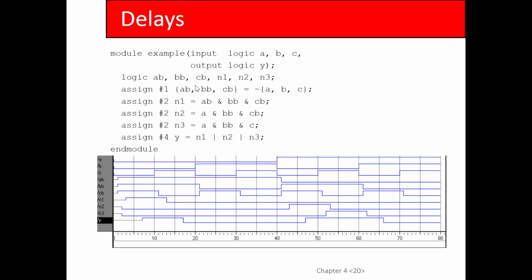The problem is that this Verilog is now non-synthesizable. You cannot synthesize any Verilog code that has any delay information in it. But if you synthesize Verilog and back annotate the delays in, that allows you to model code that you've already put on a specified technology. Does that make sense? It's kind of esoteric, and this is not very common.